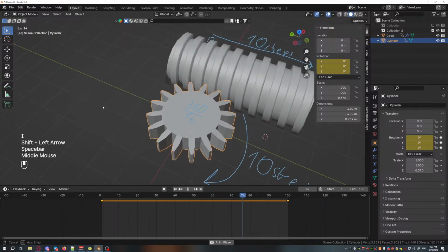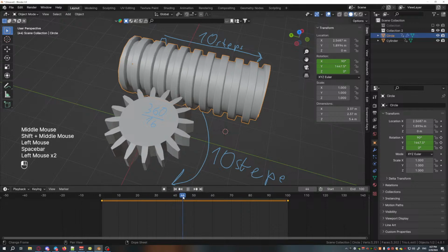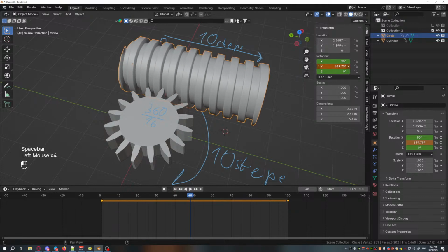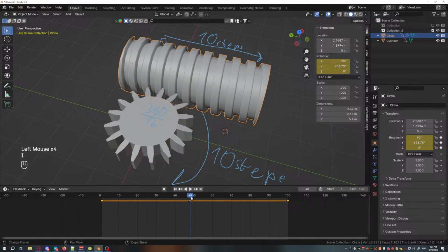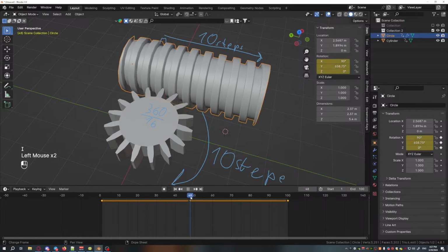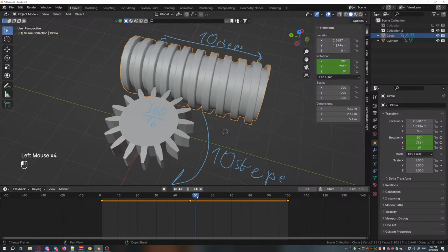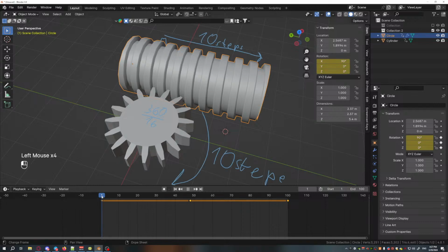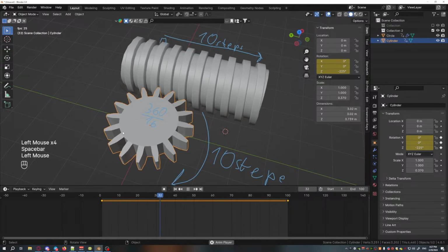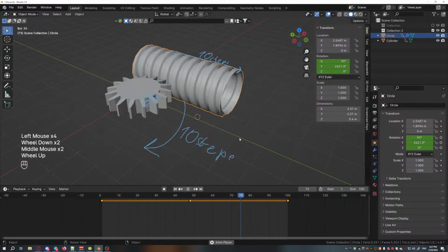Well, looks good enough. But if I wanted to change this animation slightly, for example, if I wanted it to start slower and then pick up speed later, I would add an intermediate keyframe there so that it only makes 2 revolutions during these 48 frames and the rest 8 revolutions after that. So it starts slow, picks up speed later, but this gear is now asynchronous with this thing. It may be, now it is still very noticeable.